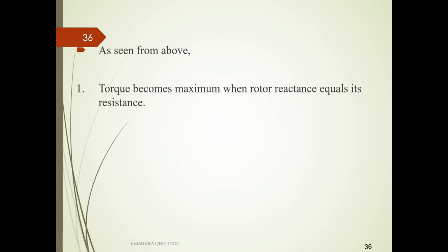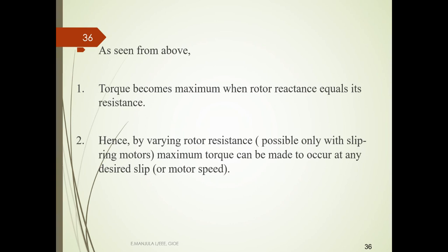Hence, by varying the rotor resistance, possible only with a slip ring induction motor, the maximum torque can be made to occur at any desired slip.